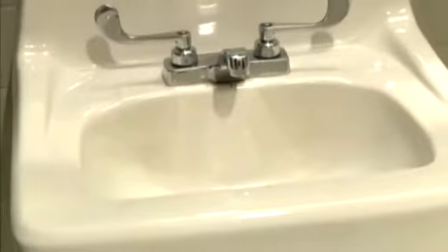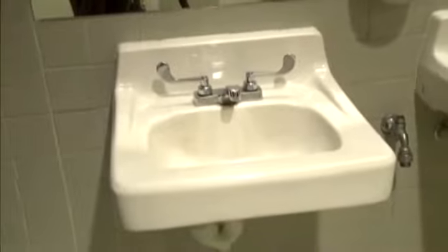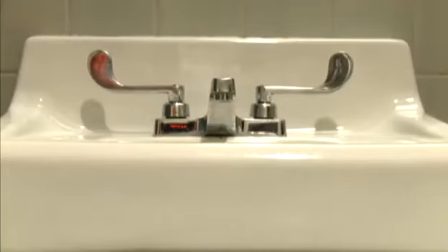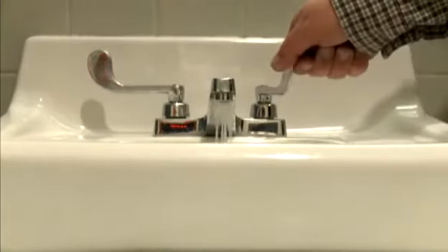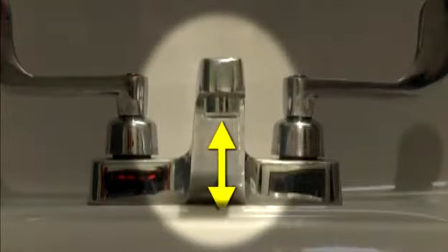Air gap. Air gap is the most effective way to prevent a cross-connection by a separation between a potable water source and a non-potable source because air disrupts the flow. An air gap is not a device. Rather, it is simply physical space.